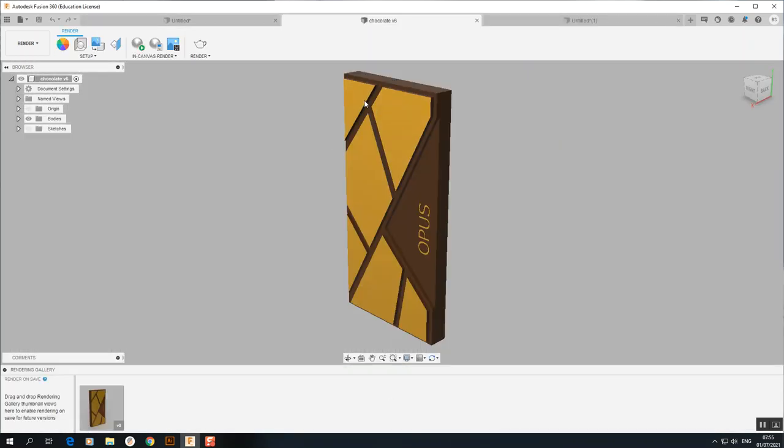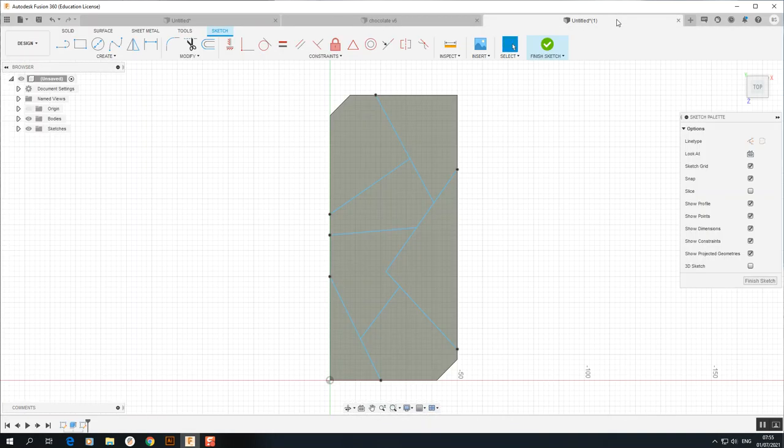So that represents these lines that would appear in here. And then what I want to do is create that little yellow bit. So to do that, I want to offset. Offset basically creates an inner line, so to speak. It'll copy whatever the outside shape is and add an inner line.